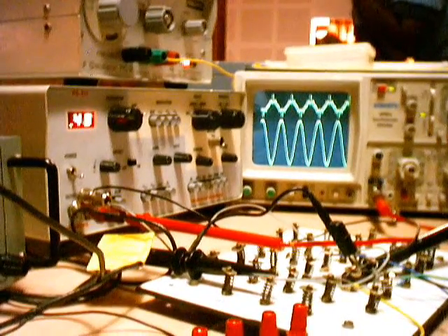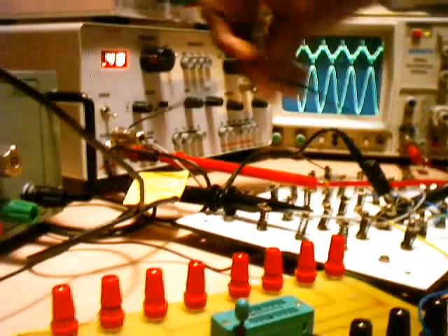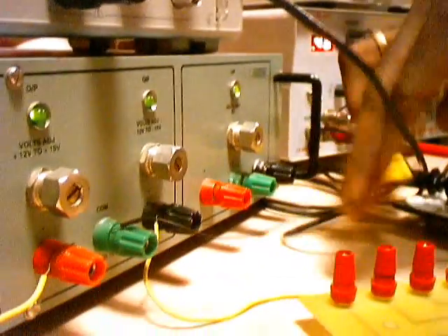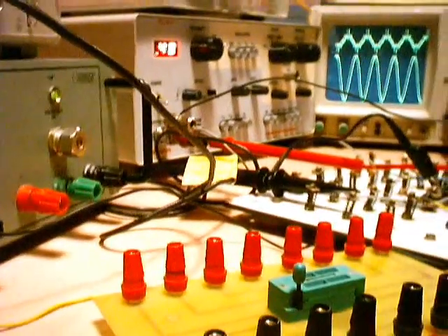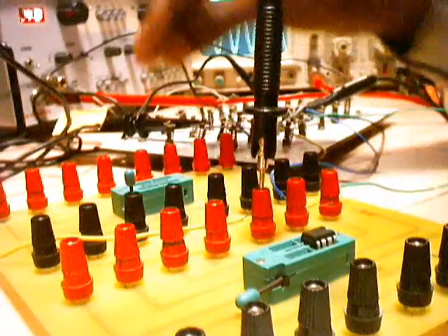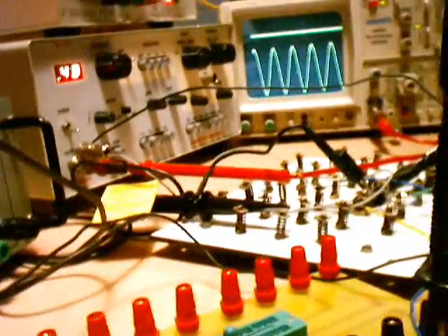One important point to note here is that while making the connection, ensure that the ground of your signal generator is connected to the ground of the op amp. If you are not getting the output, first check the supply voltage of your op amp, whether it is 15 volts at pin number 7 and minus 15 volts at pin number 4. Ensure that you are not missing the ground connection of the op amp, which you usually miss. This is a common ground. Ensure that it is connected to this ground, so there should be 2 wires coming to the ground point. With respect to the ground, we are going to measure all the voltages.